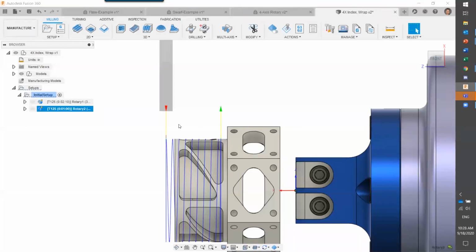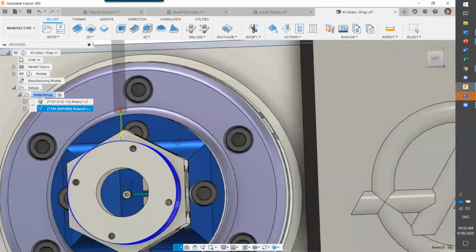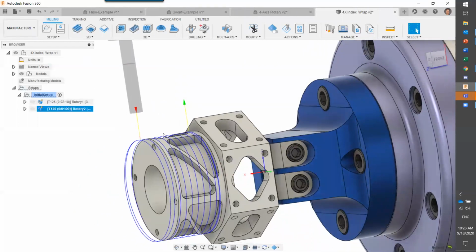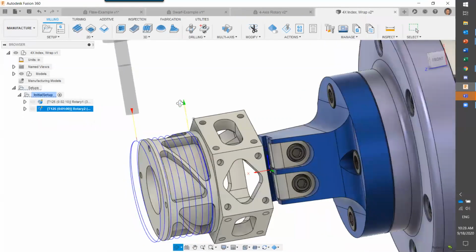So a common question I get is, can you do the rotary toolpath in multiple step downs? Unfortunately, you can't as of right now. Really, there's a workaround though. If you just do multiple toolpaths with stock to leave, that theoretically gets you the same result. It's a hassle though, so again, I normally don't recommend that. I would probably try to think of a different way to machine that, or at least do a roughing path for that. Rotary toolpath is really just going to be a finishing strategy, right?